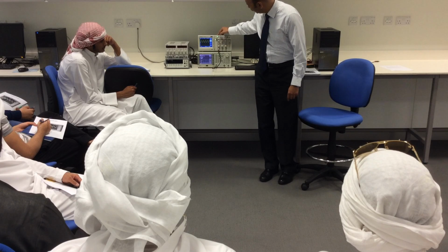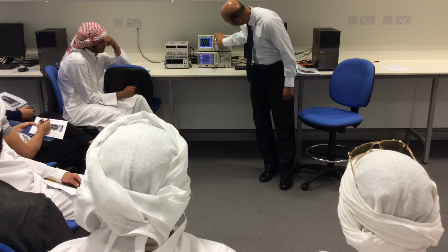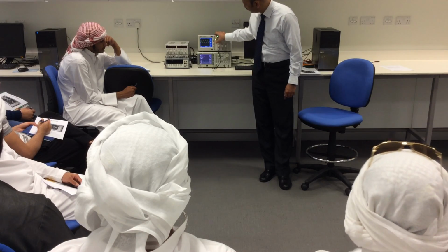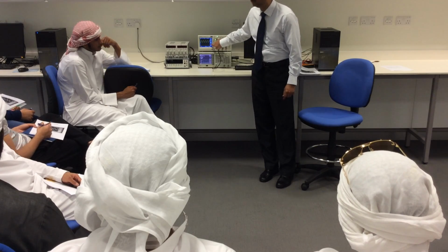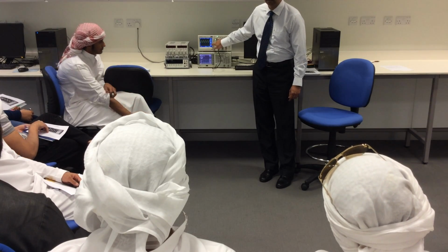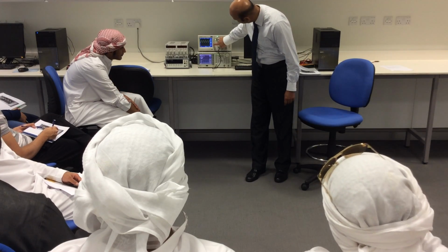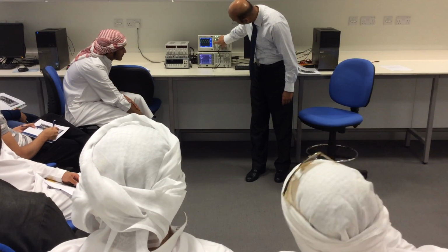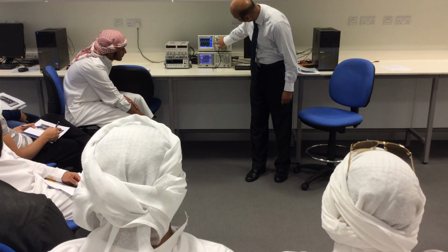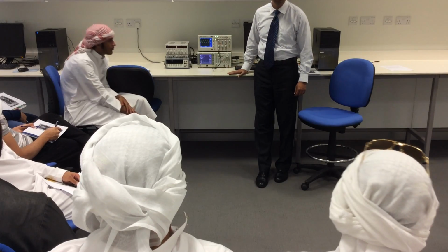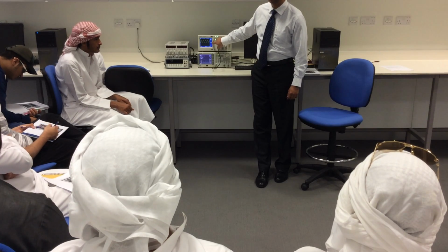There is one more thing which we need to be careful about. You press on number 1, and you see right now it is a 10x probe. You just need to make sure of a few things. It should be 1x. So press number 1, and you come here, you press this. So this is 10x attenuation. We want 1x. So press number 1, and attenuation should be 1x.